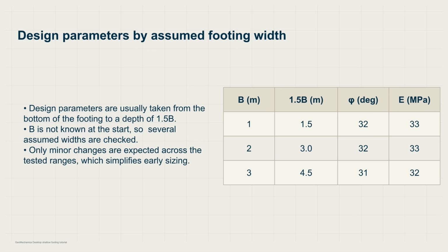We test several footing widths because the final dimension is not known initially. Design parameters are typically determined up to a depth of 1.5 times the footing width.